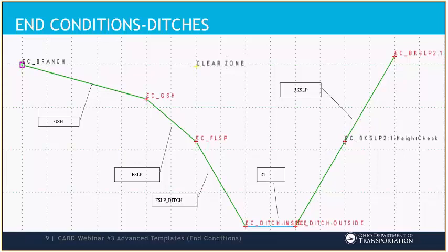But you can insert a point here and call it your height check, and you can give the height of the ditch, your minimum ditch requirement. And what that does is once your back slope falls lower than that minimum, then it won't solve anymore. So if you don't care about that, then you don't have to have it. So that's the setup with the ditch.